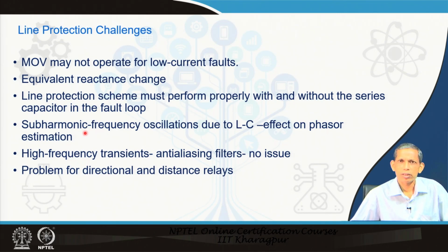Furthermore, with the introduction of C in the line, which has series inductance, this LC combination gives us subharmonic frequency component oscillations. Therefore, the signal as seen by the relay will have these components, which will affect the phasor estimation process, as we have studied in phasor estimation by one cycle DFT or so. The frequency response we have seen shows that the subharmonic component affects the performance of the phasor estimation technique.